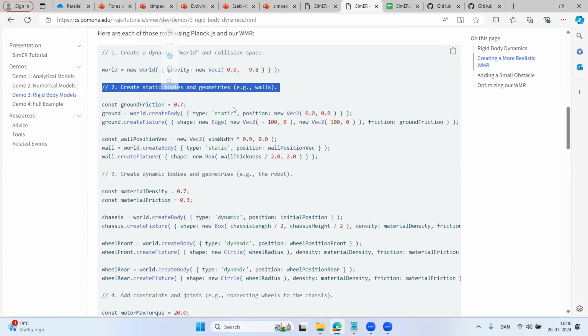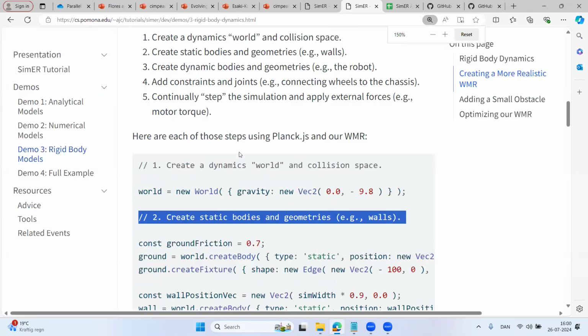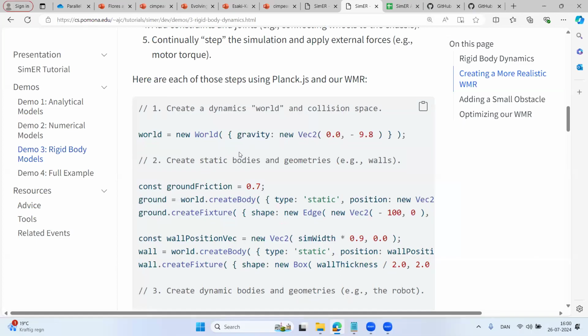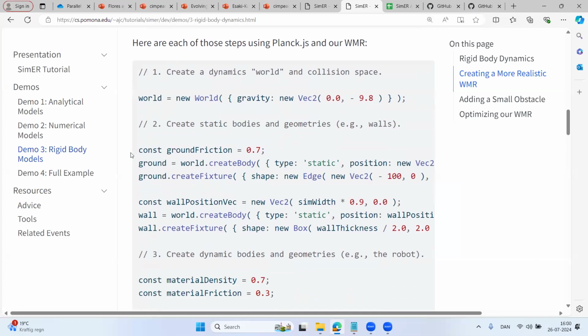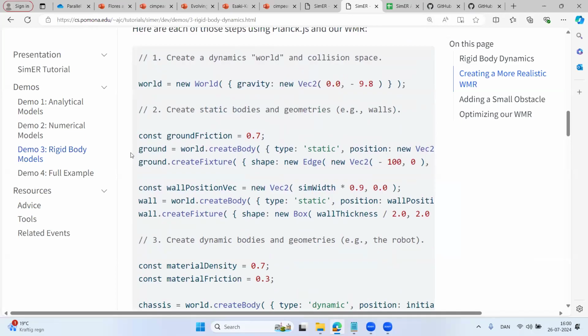In this case, I usually start with my static things, so things that don't need to react to physics. You'll almost always have some utilities for things that are easier to simulate. If it's static, it doesn't react to gravity, and so it's cheap and easy to work with. You don't need to worry about its mass, essentially. Instead, things just collide with it.